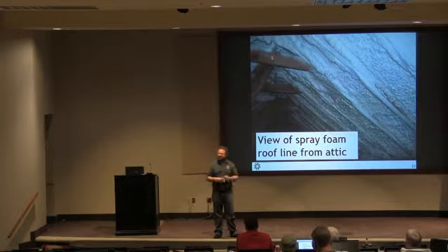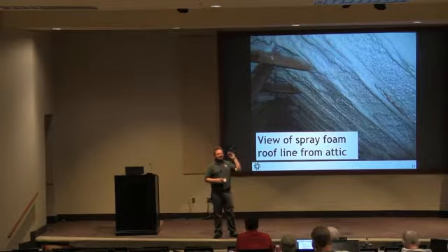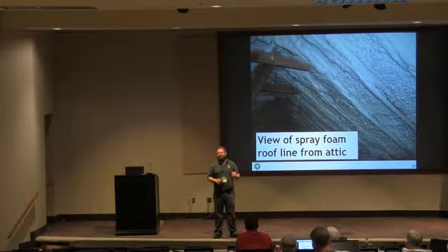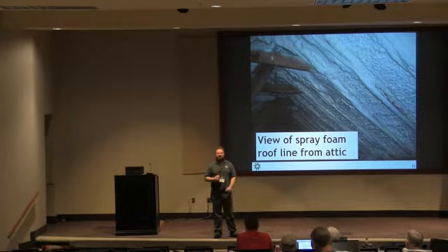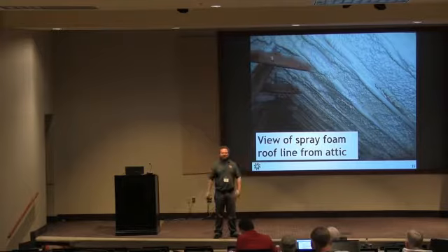On the other hand, if I'm a manufacturer and I don't make spray foam, I make an alternative, more traditional insulation product, and I make a roof shingle, guess what? I don't want to warranty my roof shingle with somebody else's insulation installed. So in order to get around that, I don't warranty an unvented assembly. Sneaky, but that's the gist of it.